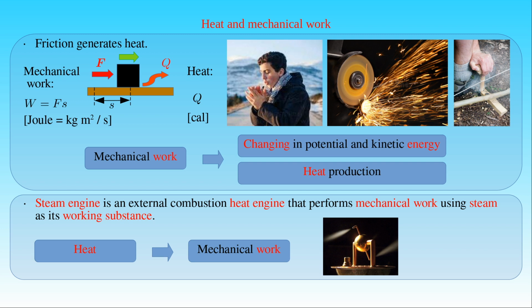The photo shows the reconstruction of the original apparatus, which was a hollow sphere mounted on a pair of hollow tubes so that it could turn on the tubes. The tubes were attached to a sealed cauldron filled with water which was placed over fire. As the water boiled, the hollow tubes provided steam to the sphere from the cauldron. The steam escaped from two bent outlet tubes on the equator of the ball pointing to opposite directions. As a result, the ball rotated about the axis passing through its mounting points, and converted heat into rotary motion. However, this solution was very inefficient at producing usable mechanical work, and the invention was never developed further into an engine applied in everyday life.